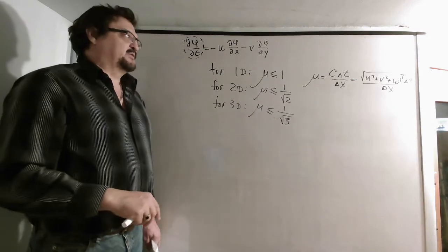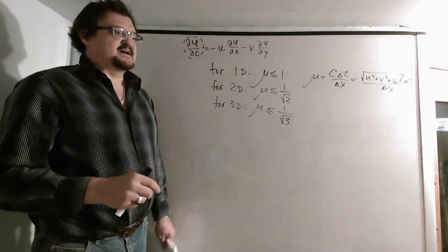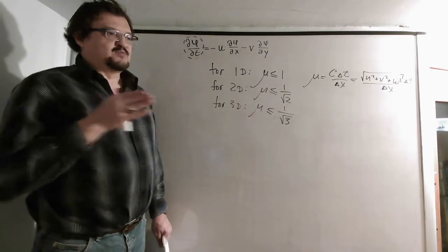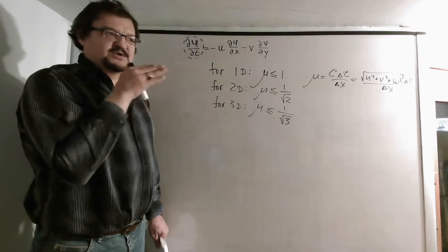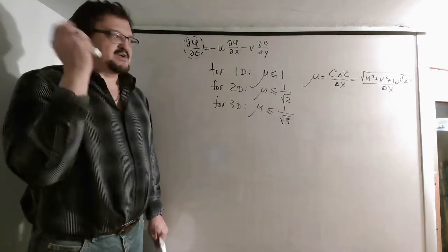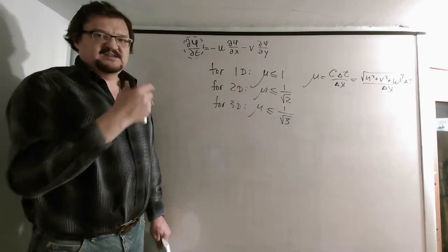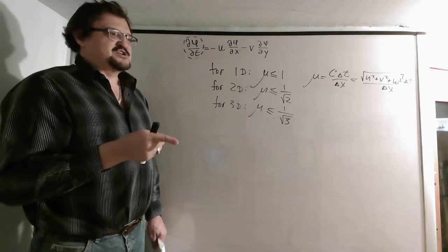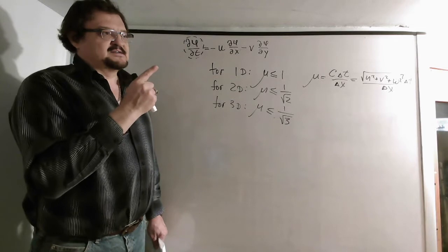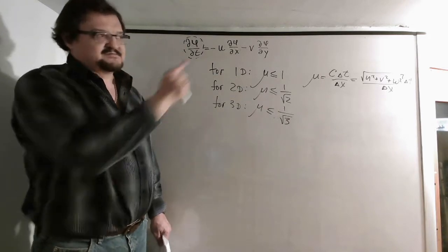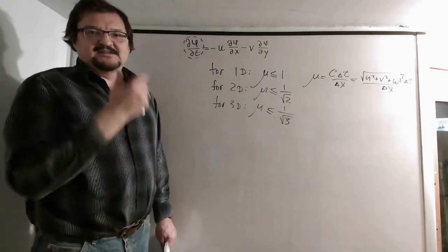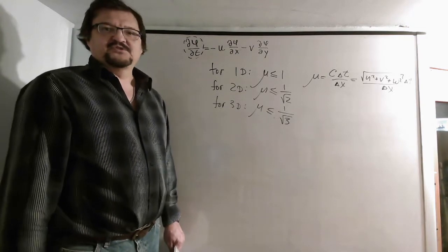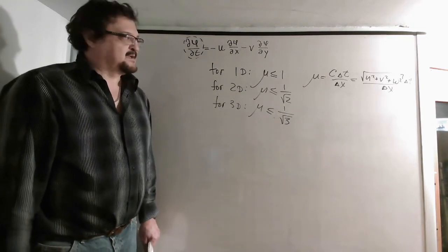When you build a model, you make a test case. Say everything is in one direction, along the x, the wind is in the x direction, and you transport something with your scheme and see if it's stable for your criterion. Then you change the direction to diagonal, in all three dimensions, and see at which Courant number your model blows up.